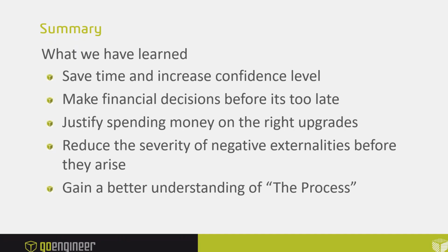recommendations from injection molders, and they might say, well, we need this and that and this and this. And be like, well, no, I really want to have 6 cavities on this mold, so we need to make sure we do that first, and then we can do some upgrades to hot runner systems after the fact. Or maybe just use like the submarine gates instead of a hot runner, right? So that it ejects automatically and splits the gate for us.